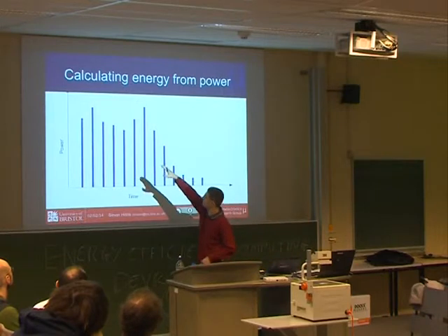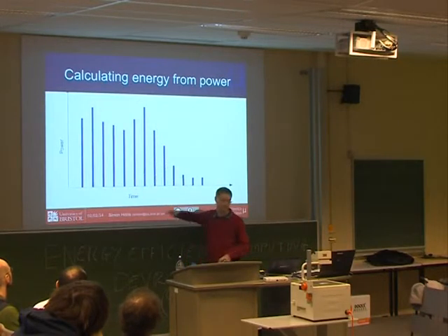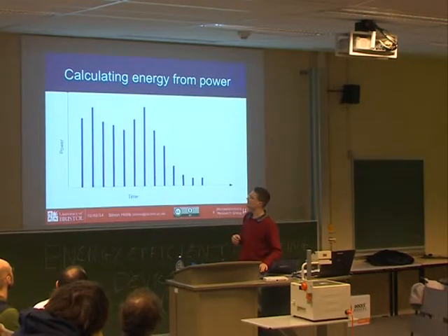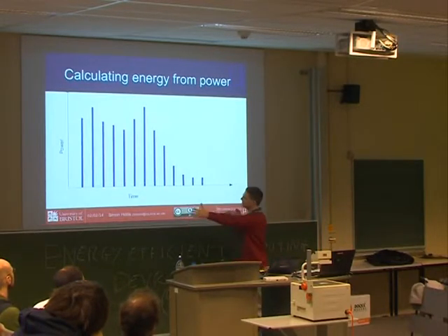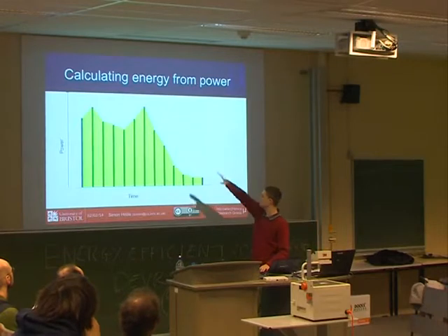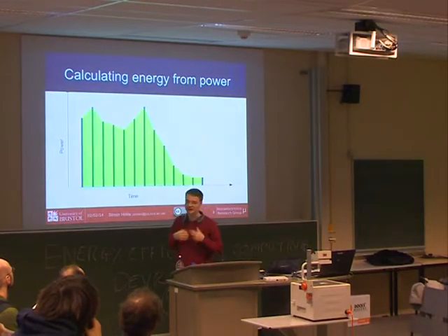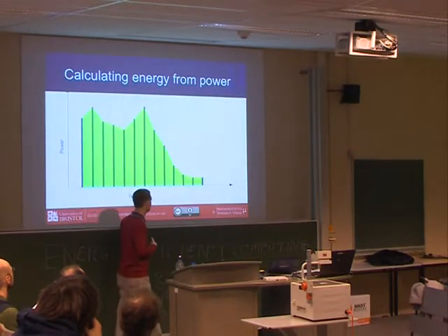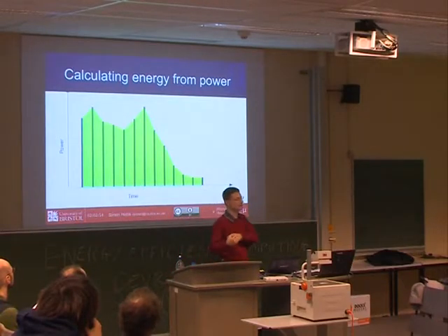You get the idea here is the system is taking a bit of power and then takes less power. And it varies around a bit. You can convert that easily into energy. If you have that set of measurements, you've got a set of power measurements now through time. You can say lots of things about the power consumption of the device. You can also then perform the integration process, which just measures the area under the curve, and now you have energy. So the area under the curve is the energy, from the measurements of power.